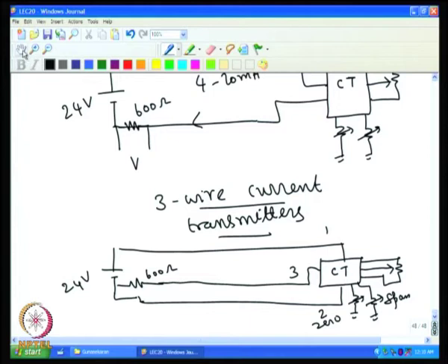Normally what is done is that you keep the potentiometer at one end and adjust the zero to get 0 milliampere in this, then take it to the other extreme and adjust the span to get 20 milliampere in this line. This is done repeatedly 3-4 times, one end for 0 milliampere, the other end 20 milliampere, adjusted using the zero and span pots.